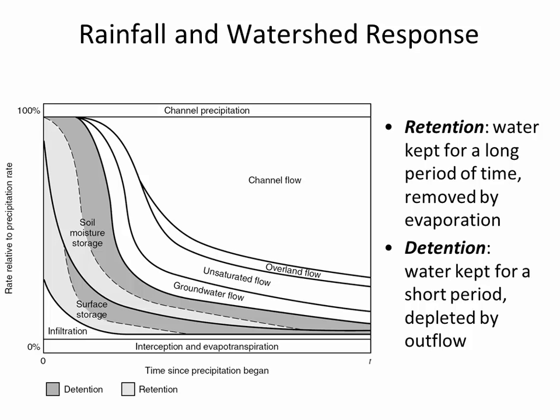Well, one of the first things that happens is it fills up surface storage. So surface storage is going to be things like puddles at the surface or wetting the surface of the ground, like getting the concrete wet before the water is moving over the surface of the concrete.